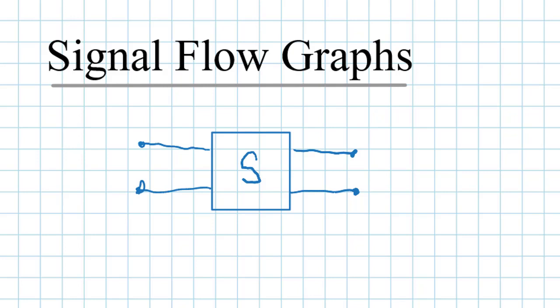And you recall that S parameters are defined by an input and an output wave at each port. So there'll be an A wave at port 1 going into the port, and a B wave coming out of the port. And the same at port 2, there'll be an A wave associated with it, and a B wave coming out of port 2.